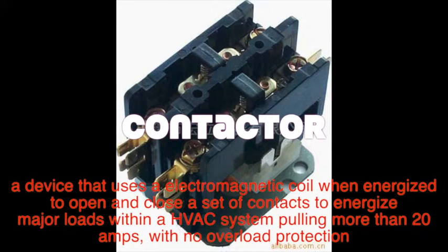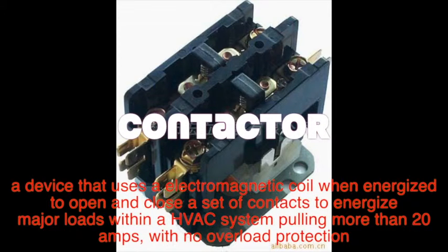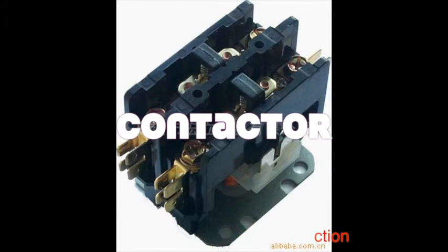Contactor: a device that uses an electromagnetic coil when energized to open and close a set of contacts to energize major loads within an HVAC system, pulling more than 20 amps with no overload protection.